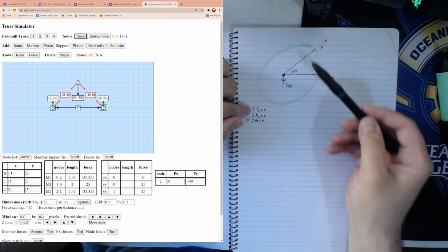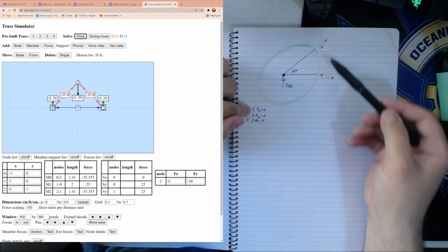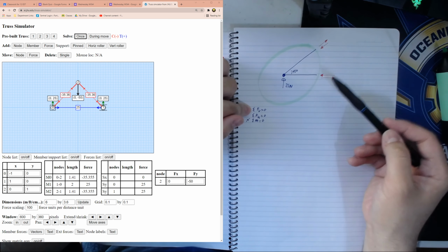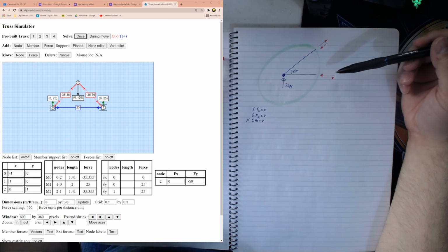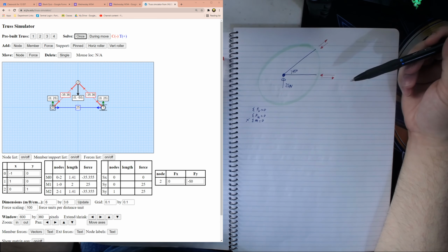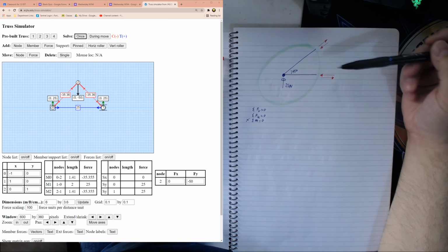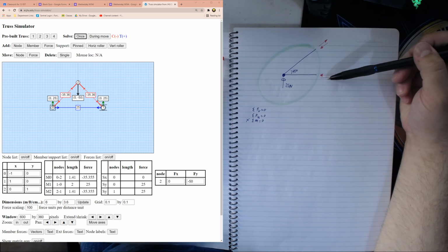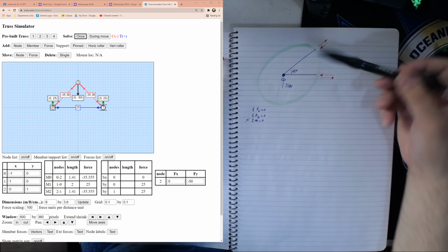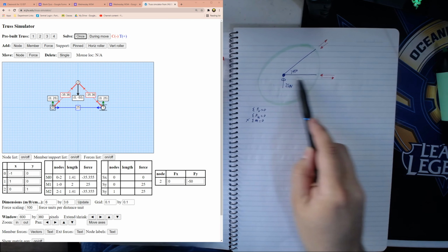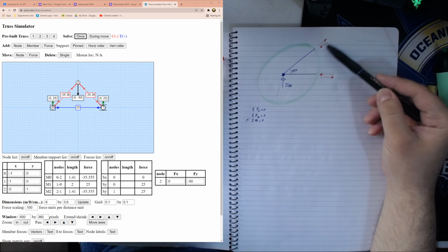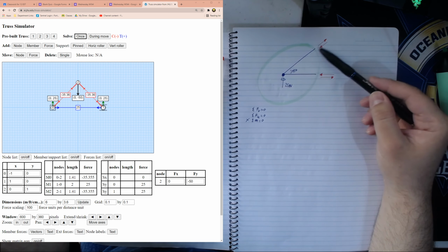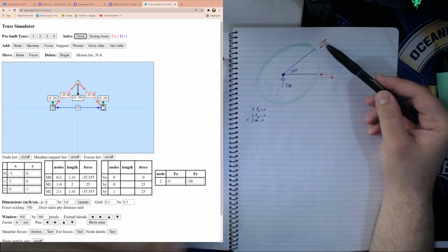This is where we say, well, okay, we have these pairs of forces, either this one or this one. Which one of these two forces can in any way impact a vertical force? This part over here cannot affect a vertical force because it is purely horizontal. No matter how much force we put in here, it's only a horizontal component, so it's not going to interact. This one over here can interact because it's diagonal, so it's going to have part vertical and part horizontal components.